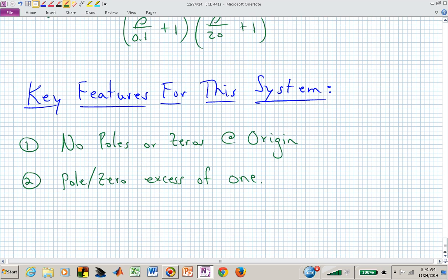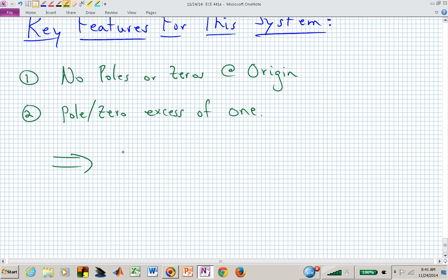What does that tell us about the Bode plot behavior as we get higher in frequency? What's G in dB going to be doing? The magnitude, it's going to be sloping, isn't it? As if you just had a single pole system, and if you have 1 pole, what's the slope? That's minus 20 dB per decade. Meaning when we get to high frequencies, we should see our magnitude rolling off at 20 dB per decade, being consistent with that pole-zero excess of 1.